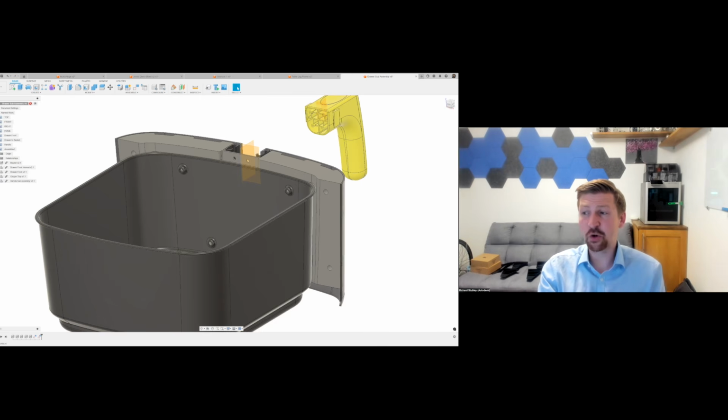The key thing with joints is you're defining the location and the movement in 2 clicks. Works brilliantly if you have those 2 clicks. If you don't and you need to build up the relationships over multiple pieces of geometry, that's where you're going to go to constraints. I'm not here to tell you what you should use. Everything's a tool in the toolbox. You can use a spanner as a hammer if you really have to.